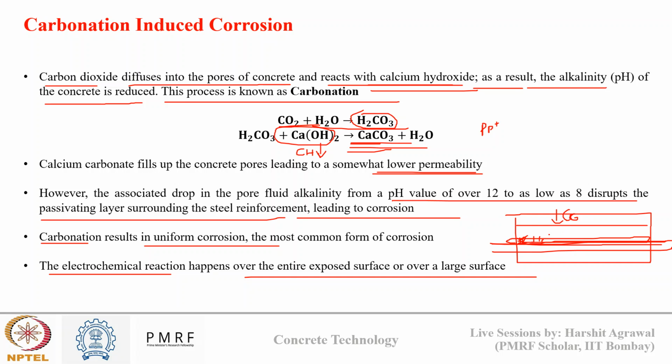In such cases, the cracking that occurs due to corrosion appears very fast at the surface. That's why we say that the cracking due to carbonation induced corrosion can be detected at very early stages.